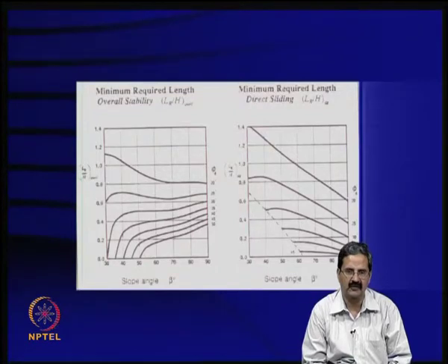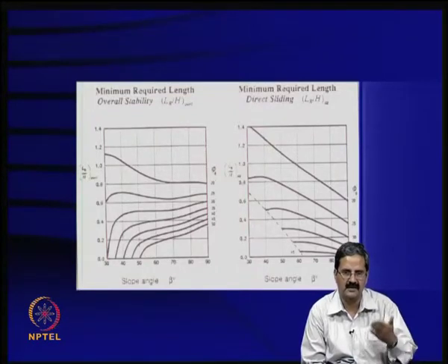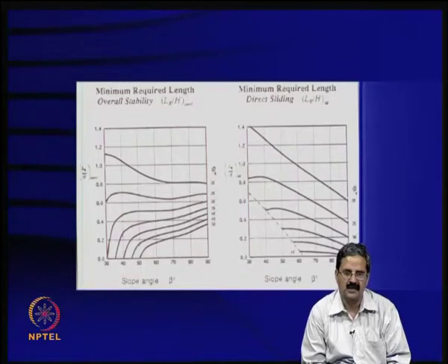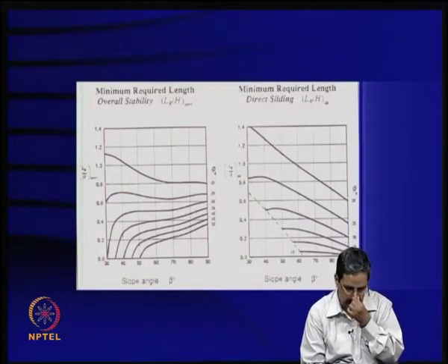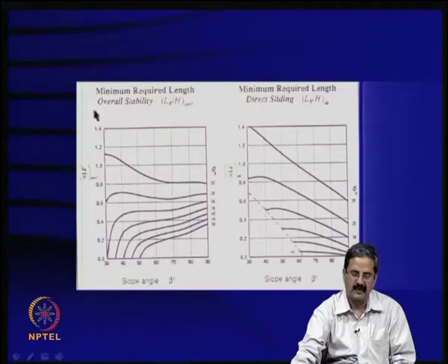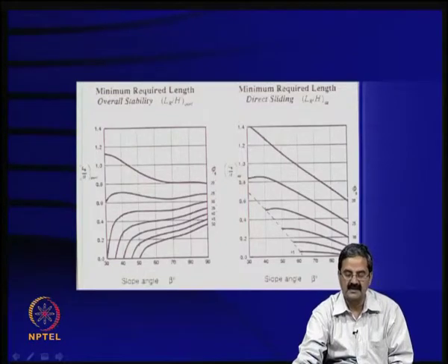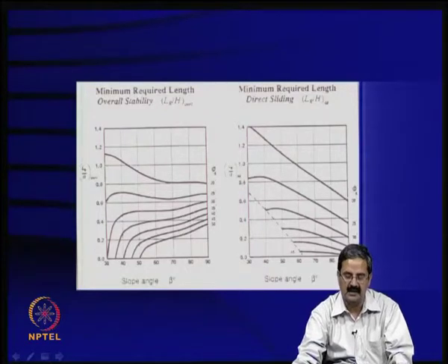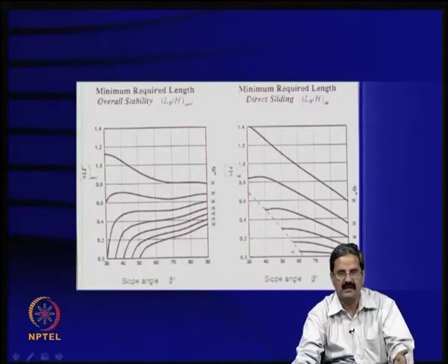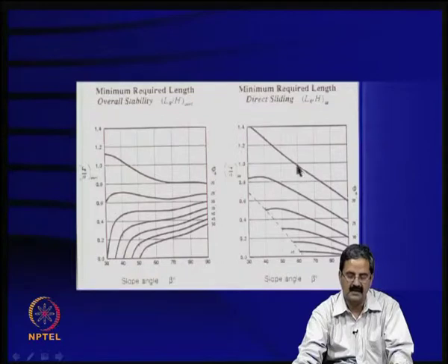So, when a retaining wall failure happens, there is a sort of logarithmic parabola or whatever, it can be a logarithmic spiral, some sort of failure mechanism, and that is the reason to calculate the forces that are acting on the retaining walls, or even in slopes, we try to calculate these earth pressures.